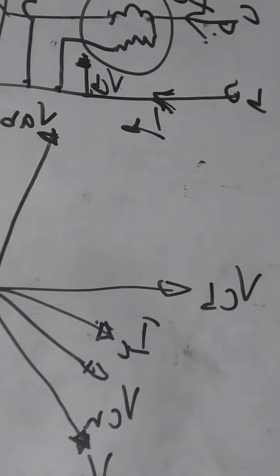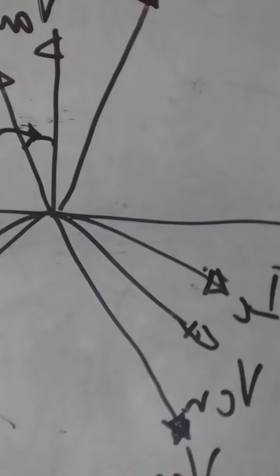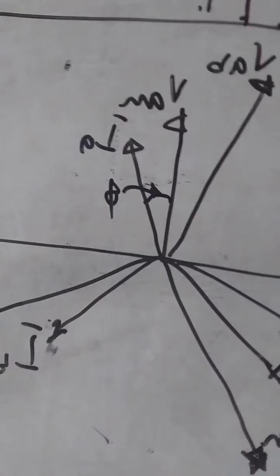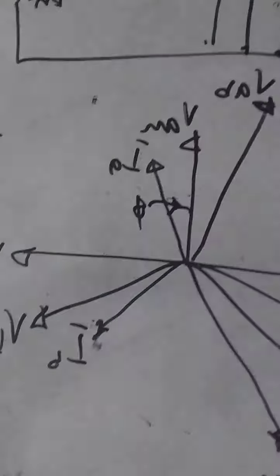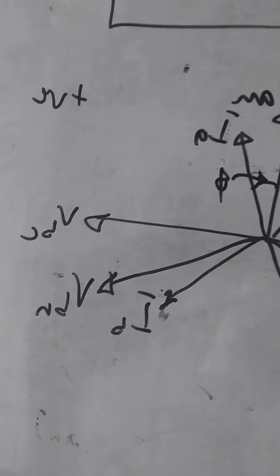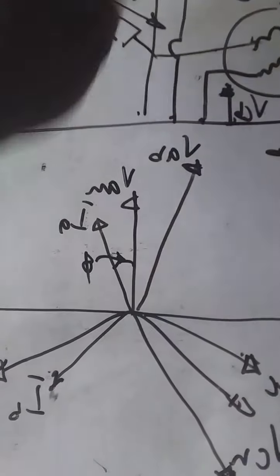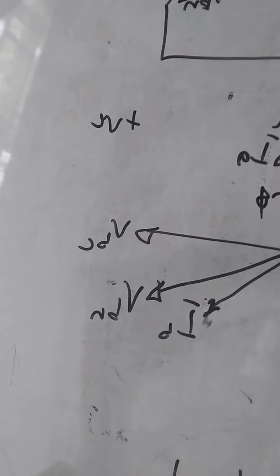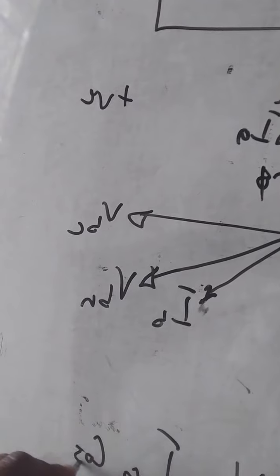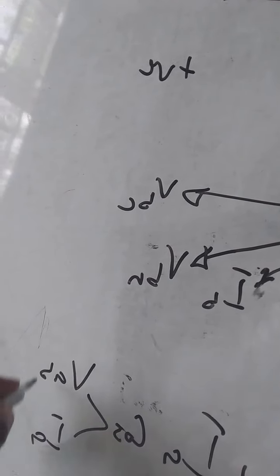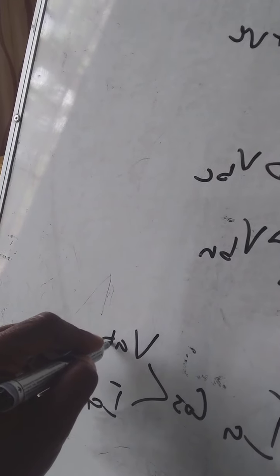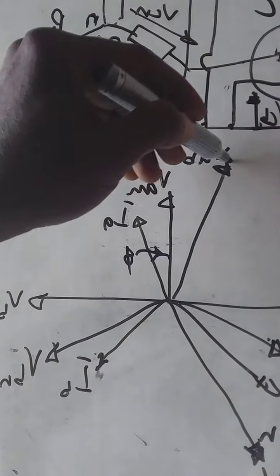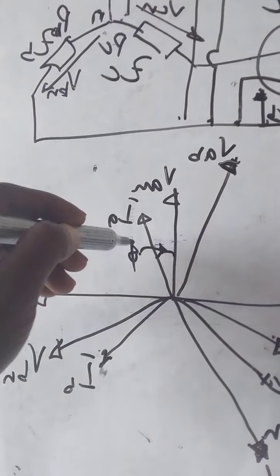Now, when we look at the phasor diagram, WA, the wattmeter reading A, is made up of the voltage and the current, the product of the voltage VAB and the current IA, with the power factor between VAB and IA. So we need to know what is the angle between VAB and IA. This is VAB and this is IA.